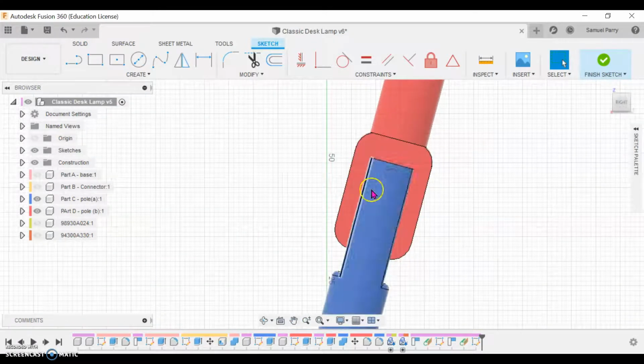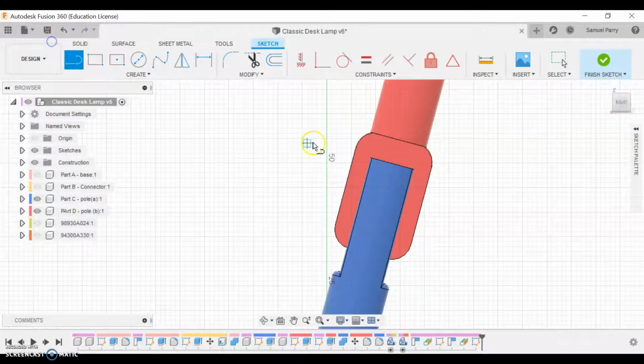And as you can see, we're going to be drawing on this now. However, what we want to do is position our hole right in the middle of this piece and in the middle of this piece. So we could do with using these lines to reference. However, with this new sketch, we can't really use them. If I click here, it's not going to lock onto the center points of these lines because the geometry from there is not on my new sketch.